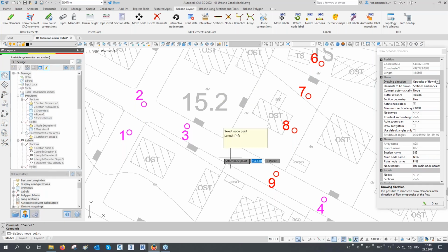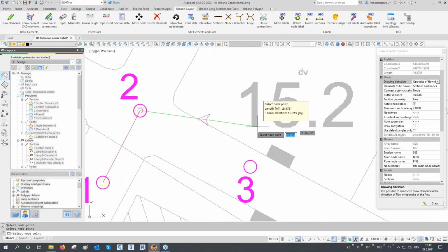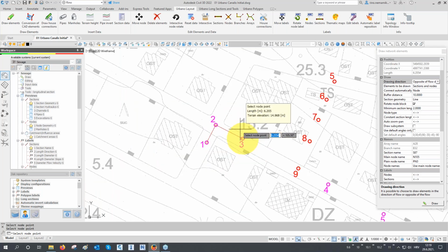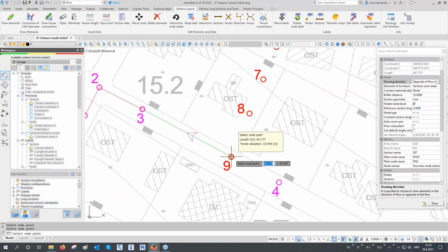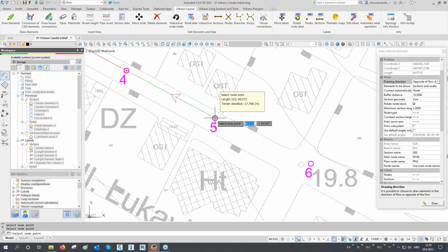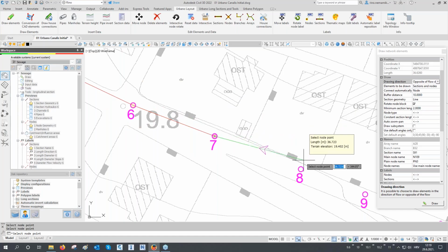And now when we click on draw, again by connecting these helping points, notice how this purple arrow is now in reversed order, suggesting that we are drawing in the direction opposite of flow direction. Now I will intentionally leave out this node because I'm snapping to node number 4. And let's now continue all up to the end and connect to existing node.